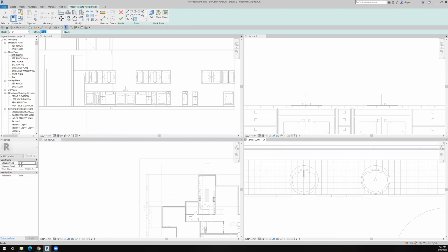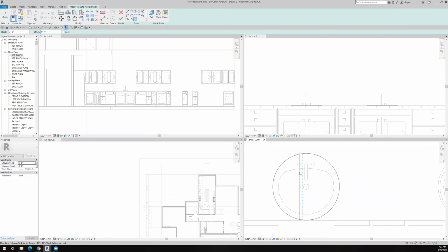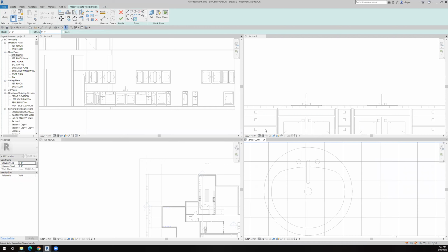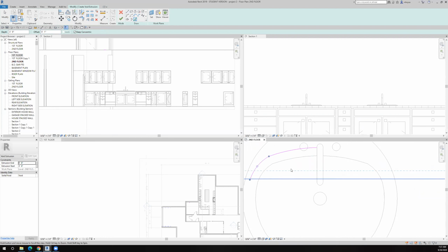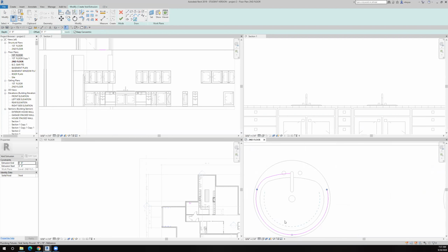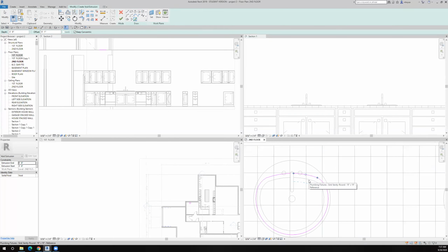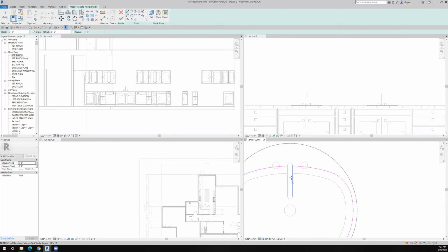It's good to see errors as well as successes, because you may find that you've made the same error as well. And now you've seen me make it, and you can hopefully identify it. What happened here was I didn't select the countertop as the object that I wanted to edit, and so Revit didn't know what that void form was supposed to cut.